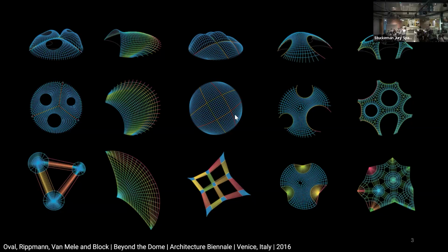Because if you were to take that regular grid and try to apply it here by just trimming it, you wouldn't be able to find a relevant shape that can carry the loads nicely here, mostly around the borders. So that was my mission, to be able to produce such meshes or networks that nicely integrate these features. Creases where you have higher forces that need to be strengthened, but that are primary load-bearing elements. Open edges that are the weaker part of a structure because it's just partially supported, and similar for the openings.